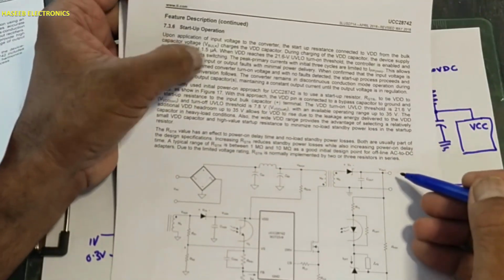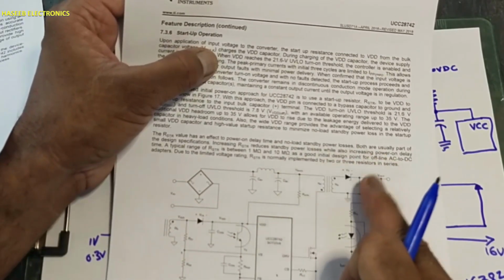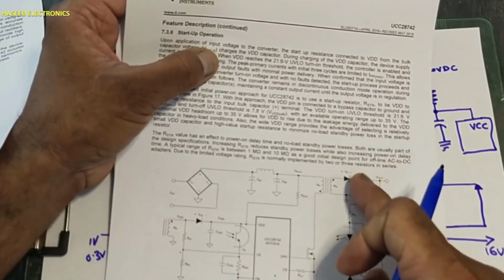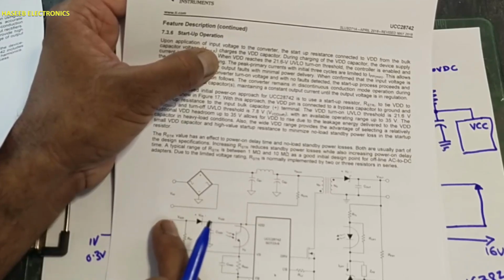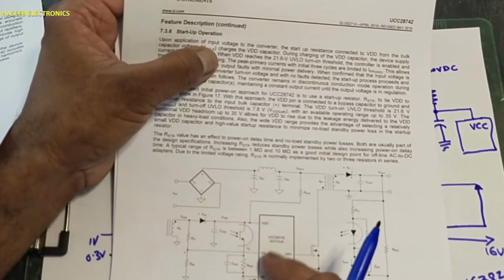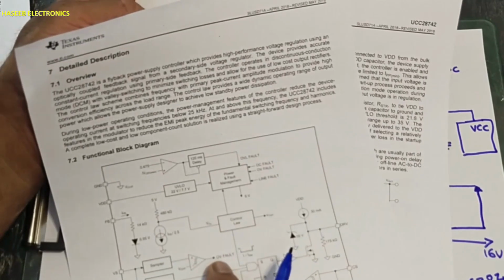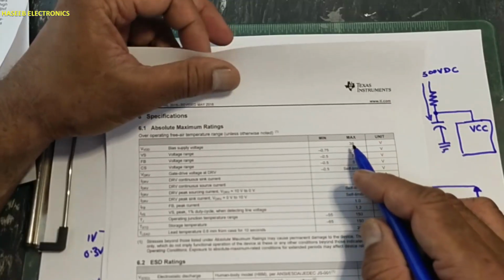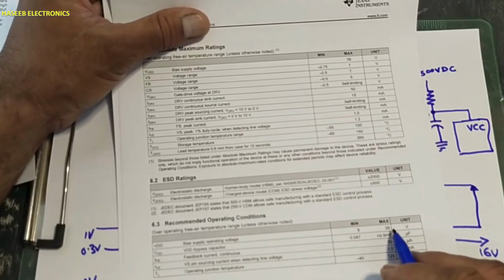If there is an overload condition, because it is a flyback transformer, in the off time when voltage is being transferred in this winding, it will cause the voltage to increase in this winding as well. So if there is any spike, that spike will reach here and this IC will generate an over voltage condition. That fault is due to load spikes, the OV fault. So maximum 38 volt, and the allowed voltage supply range is 9 volt to 35 volt for this chip.